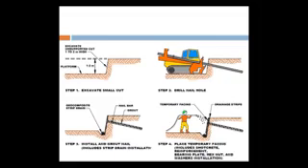Here it is. You can see step 1, excavate small cuts 1.2 meter from the platform. Next, drill the nail hole by means of a machine. Then the third step, install and grout the nail. Now he is doing shotcreting.